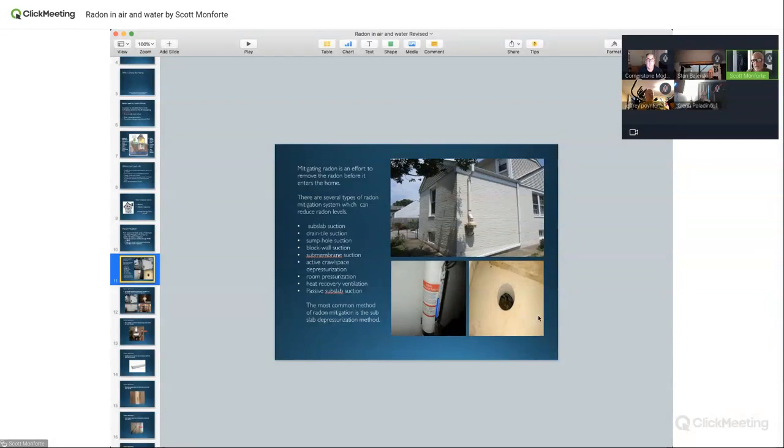We core about a 4-inch, 4.5-inch hole. Some guys will core 5-inch. I like a 4.5-inch hole, dry core. And then I have a little tool I get under there, and sometimes it's a screwdriver, and we take out a bell, like picture a bell upside down. It's not so deep, it's wide. And we want to be by the footings.